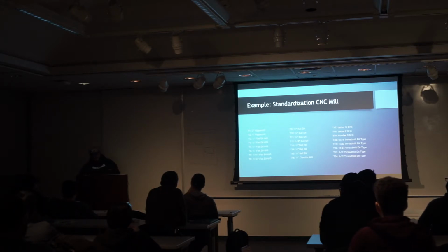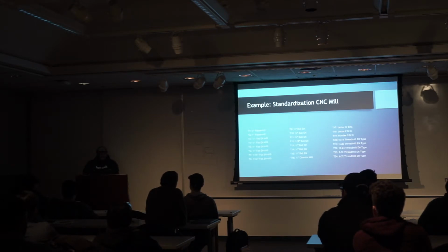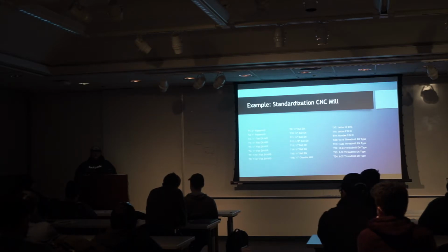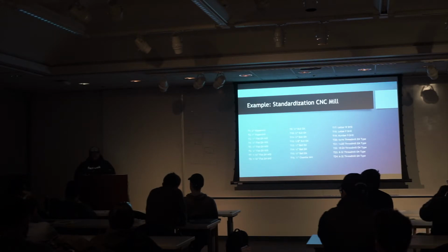From my experience with this tool list, I could have machined 95% of the parts I made for SAE while I was here. So it's pretty good. But again, if you have these tools built and measured, if you have your offsets in the CNC machine measured already, these aren't variables that you're worrying about, like, did I mess that up? Did I measure that wrong? And this will allow you to move faster and not spend time building tools, measuring tools, finding work offsets in your machine. This is just a specific example.